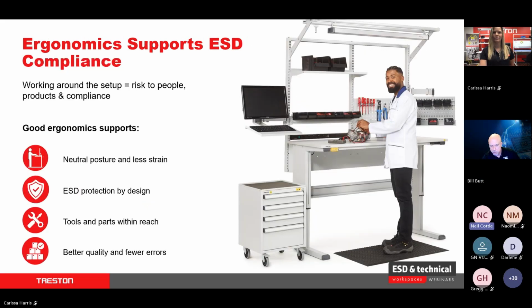Yeah, so the final point I'd like to make is that ergonomics and ESD are connected more than most people realize. They move parts closer than they should. They ignore storage locations. They may work around monitors or even reposition tools because the setup doesn't support the tasks that they're doing. That usually doesn't happen because operators don't care about ESD. It happens because the workstation makes the correct process harder than it really needs to be.